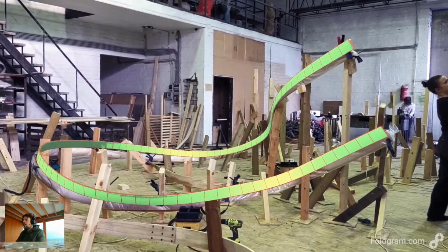And so not having a hologram showing exactly where the formwork had to go just made setting out these parts far, far, far quicker. And it's kind of an interesting idea because this is a complex double curved piece of geometry, and yet again there's almost no design documentation required in order to fabricate it. You just use literally the 3D model from the design oriented flat on the floor in order to fabricate it.